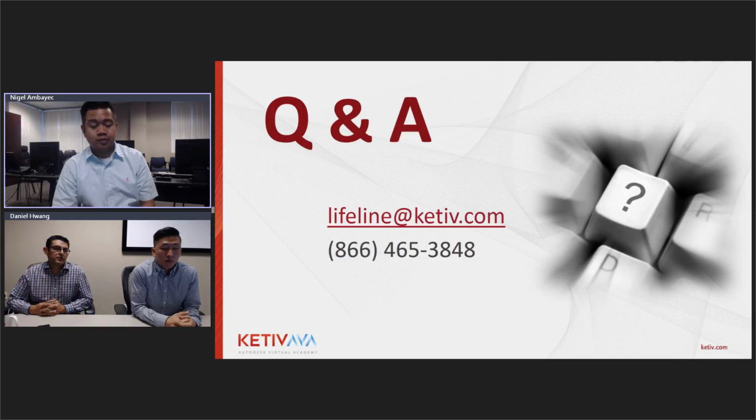So I don't think that's necessarily the question that determines which method you'll use. Basically, if you're always consistently using the same design data, I'd say use the option in the application options inside of Inventor. If you have to change from project to project, you work on different jobs with different customers, and they require different standards or different fonts or different dimension styles, then I would go ahead and change that setting through the project file. So yeah, it just depends on your particular case.